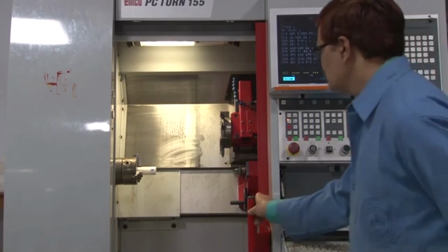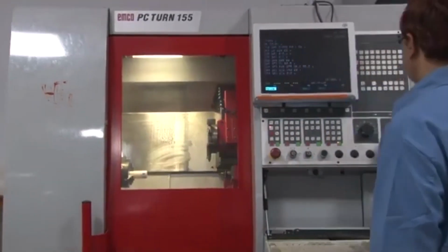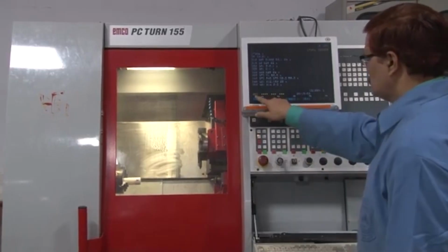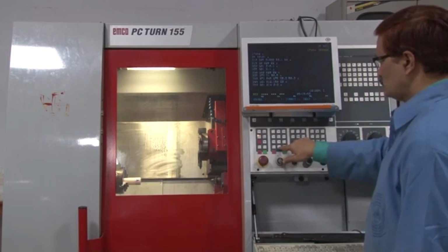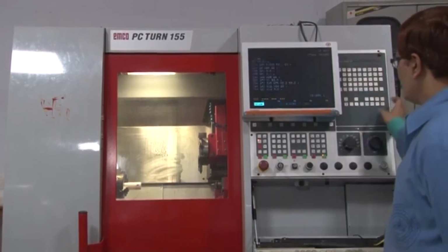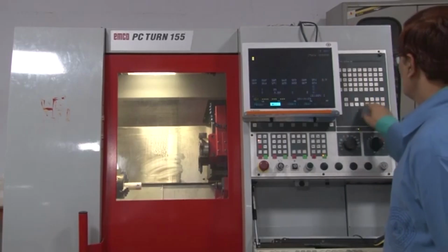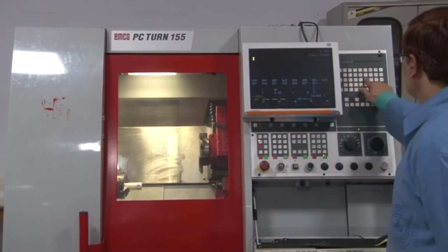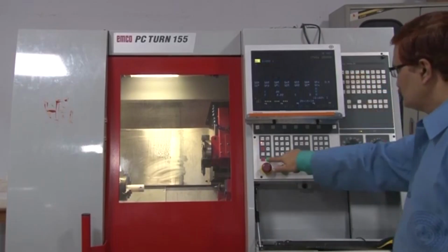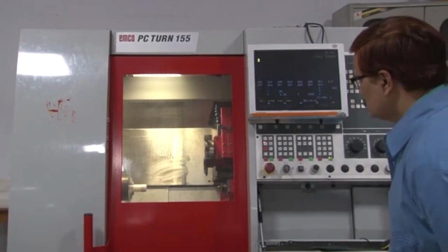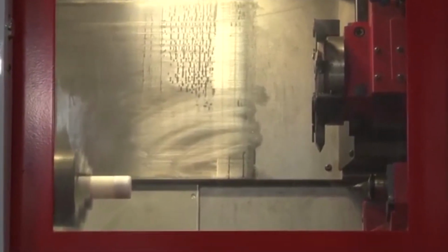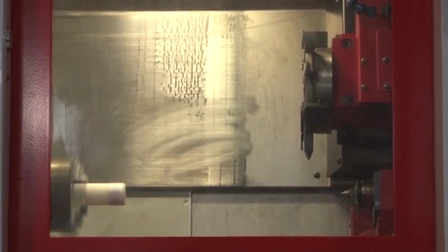Okay. So, the first step is, first of all we have to close that, because otherwise it can be potentially dangerous. Now we are putting the program, and we are putting that in the reference mode first. You can see that this is the adjustment of the axis. Then the rotation of the spindle, that command is given, and you can see the spindle has started rotating. Which direction the spindle has to be rotated, either clockwise or anti-clockwise, that also has to be programmed.